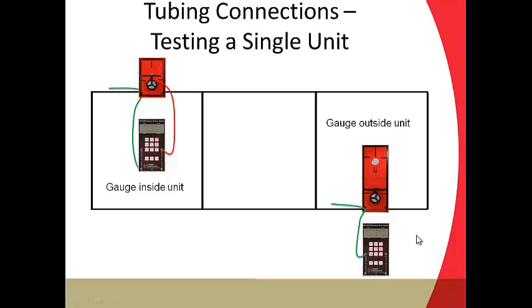In channel B, we connect our red tube to the fan the way we always do, but we need to be measuring the pressure at the flow sensor with respect to the space it's in. And when we're doing this test, if we're doing a depressurization test, our rings are inside. Our rings are inside the building. So we need to reference the inside of the building with that tube. So either we could connect an additional tube, or we could do a T connection and run one tube to the inside from those two locations.